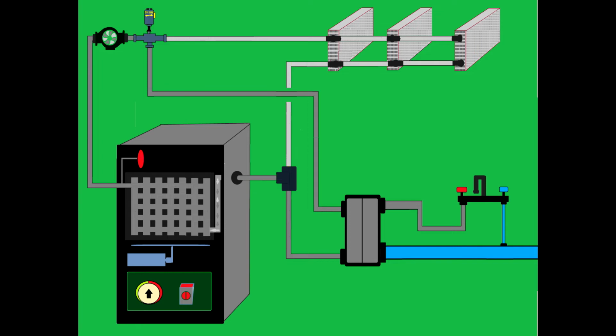which will have the capability to heat the domestic hot water instantly. What you'll see on the right hand side towards the middle, that's a tap, and anytime I'm opening the tap, the boiler will be instructed to turn the heat exchanger on, and the heating agent will be directed into this plate heat exchanger, where the hot water will be instantly heated for usage.